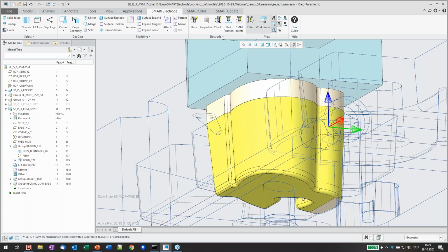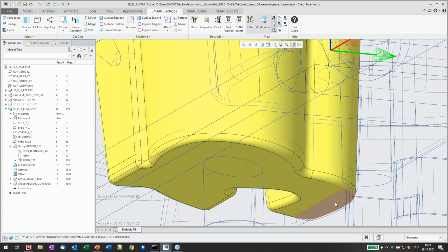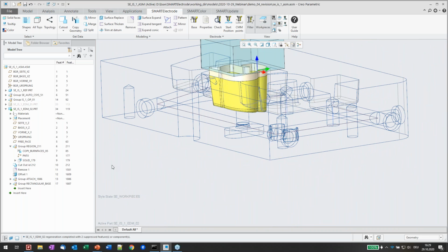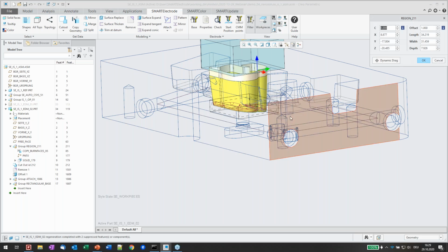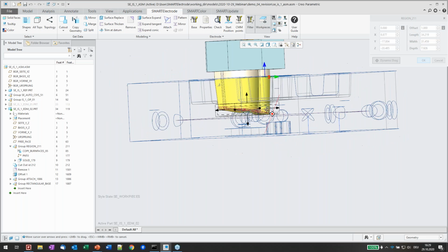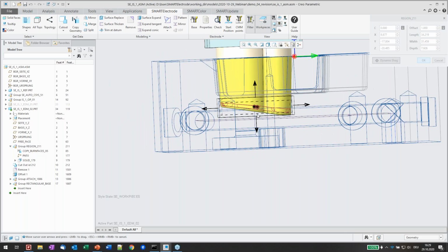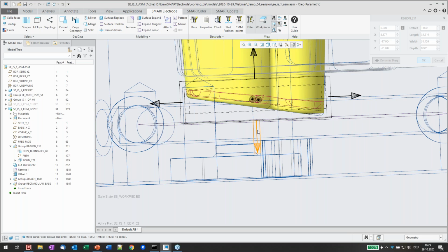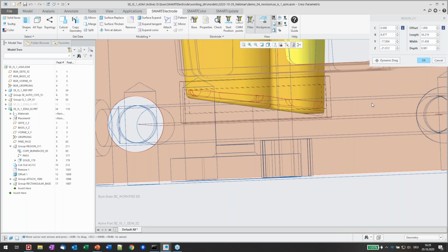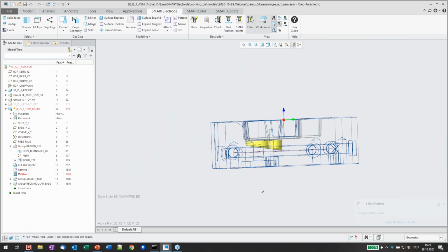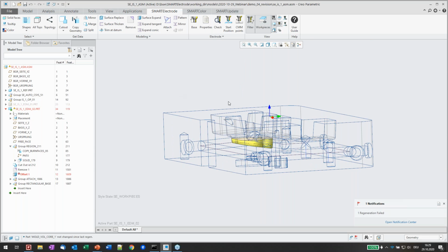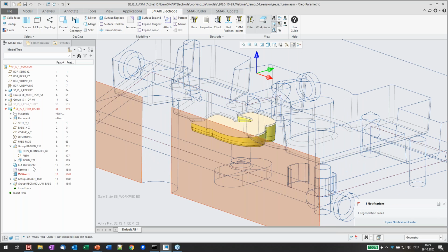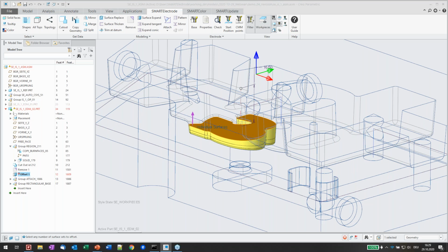We can see down here is still an area not filling the whole contour. So we need to adjust our solid. So let's get it here inside, and let's change the dimensions dynamically. So we pull that a little bit down, and it's okay again. Press OK. We may have to change the offset feature.